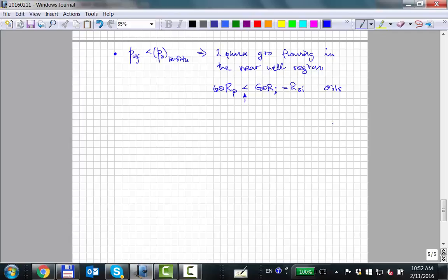For gas condensates, the GOR produced will be higher than the initial GOR, which is 1 over what we call the solution oil gas ratio in the black oil tables. We'll talk about it later. So the initial gas oil ratio of the initial fluid, you'll produce at a GOR higher than that. And it might be anywhere from 2% higher to maybe 15% too high. Okay?